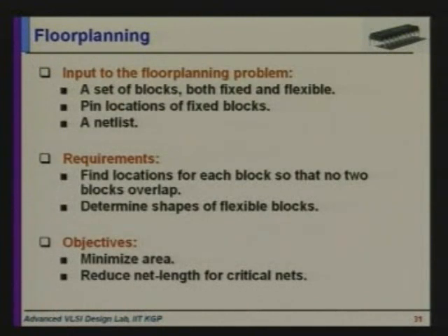Here I have a few connected problems: chip planning, floor planning, placement, and pin assignment. Rather, I come to placement first. What is placement? I have been given a set of fixed blocks. I know the exact dimensions of the blocks.